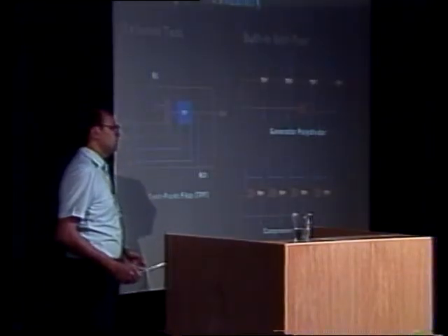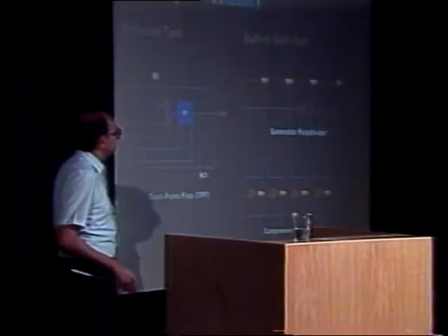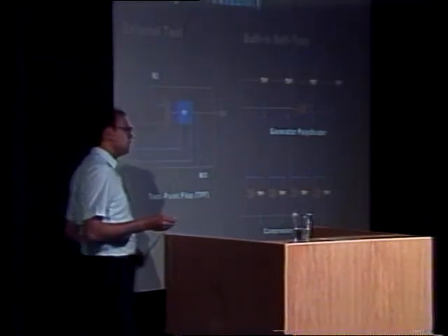Now, again, I want to point out that the test point flop is the key element in these design for test techniques, whether we are doing external test or built-in self-test. In fact, the cost of your design for test approach is directly related to how efficiently you can implement this test point flop. I don't know how many of you here have to do MOS design, but what I'm going to show you in the next couple of slides is an idea for implementing a scannable flop in MOS, and I call it system latch scannable flop.